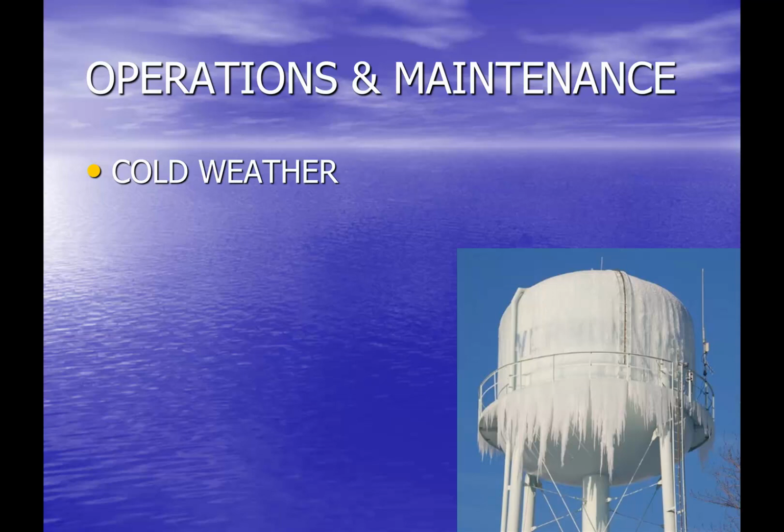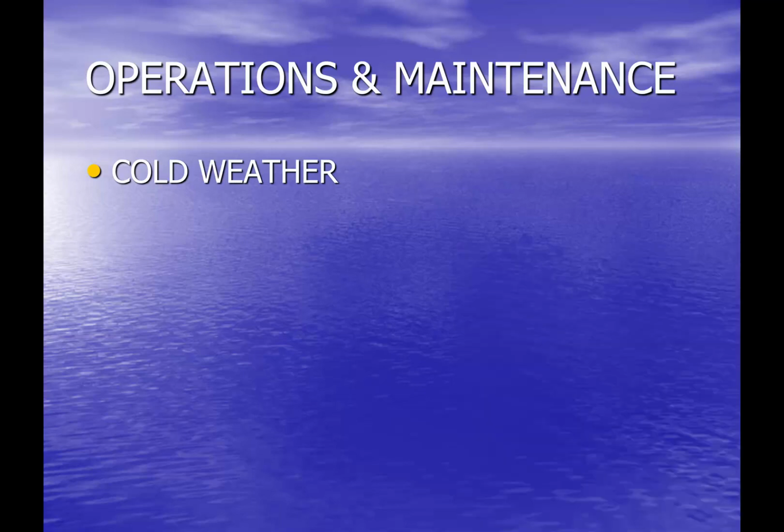So one of the ways that you avoid the buildup of ice or potential cold weather issues inside an elevated storage tank is simply by varying the water level, making sure that the water is coming in and out so it's not sitting still. As we've talked before, anytime water is moving, it's much less prone to freezing than water that is sitting still. So getting that water level moving up and down relatively constantly is one way to avoid some of those cold weather issues for especially elevated storage tanks.